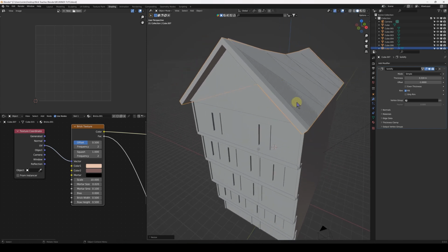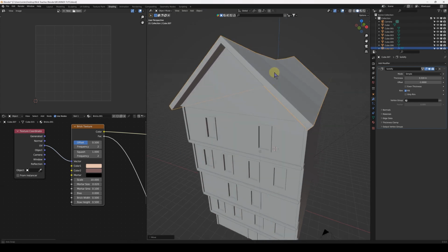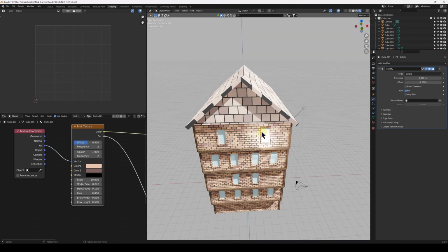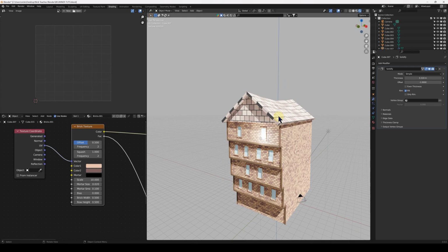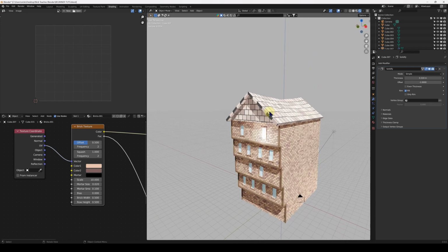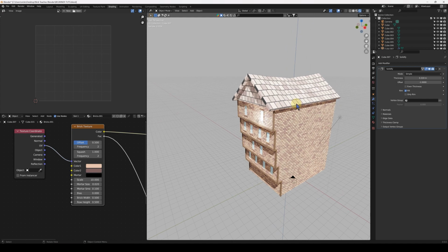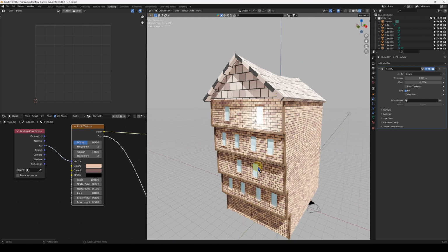And I think I'm going to move it up slightly to avoid this polygon clash. So G Z, and I'm going to hold shift until those marks disappear. There we go. We now have a much better looking roof. We're probably going to have to look at the edges, but we're nearly there, and then we'll sort the door out, job done.